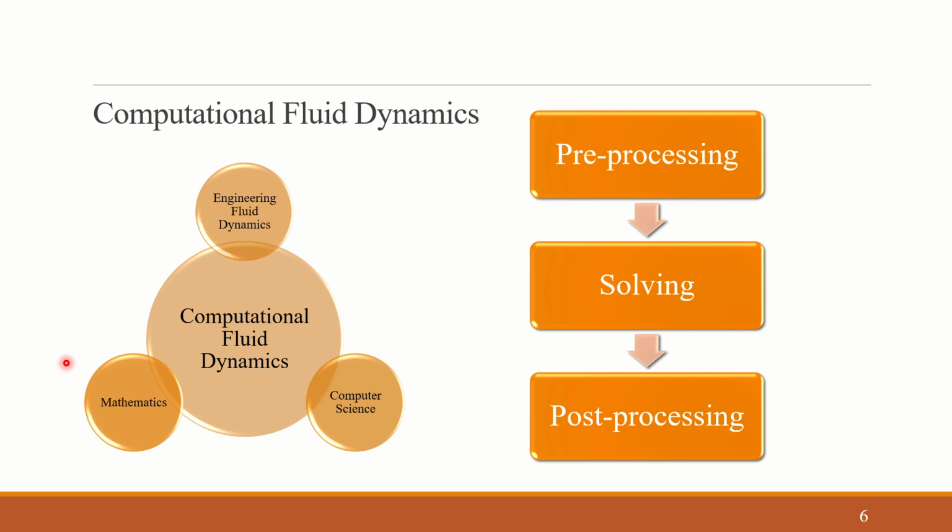What happens in CFD is that we can divide it into three steps actually: pre-processing, solving and post-processing. Let us come back to the fluid flow in a single pipe. First it is pre-processing. I am talking about the case when you are using certain CFD tools to get the solution. In pre-processing, you are about to simulate the fluid flow inside a pipe, so you need to know the pipe geometry and you need to mesh the pipe.